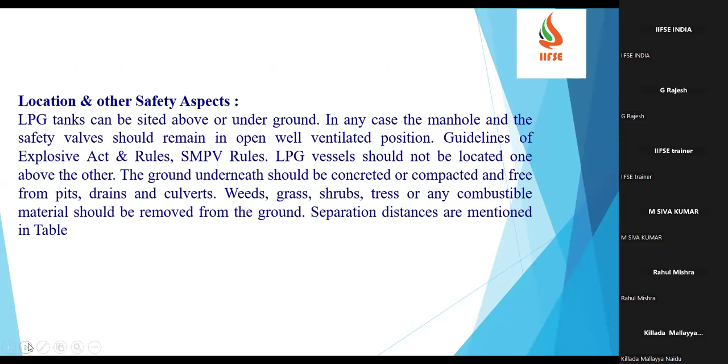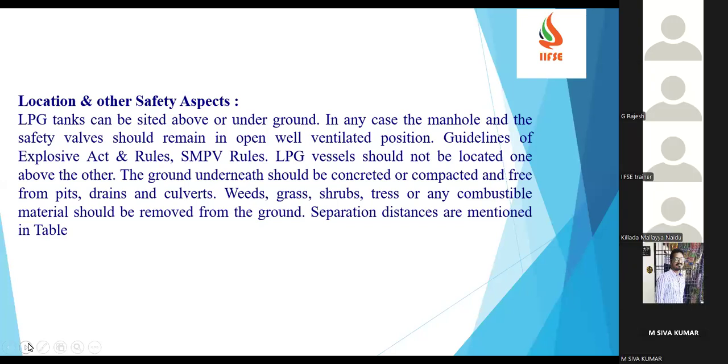There are two options we can do. Not like chlorine, it should be always on the overground. It can be done underground as well as above the ground. In any case, it should be concreted and compacted and free from pits, drains, culverts, weeds, grass, shrubs, trees and all combustible materials. So wherever you have a storage of LPG, you should maintain proper housekeeping.